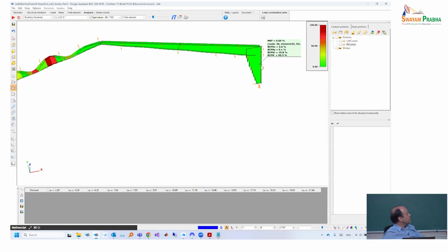If I activate it, for each of the buckling modes which were calculated, we create this map for the distribution of the deformation energies, and we assign a given buckling mode to the member which produces the maximum, obviously the 100%, so there's no hesitation, that will be assigned.